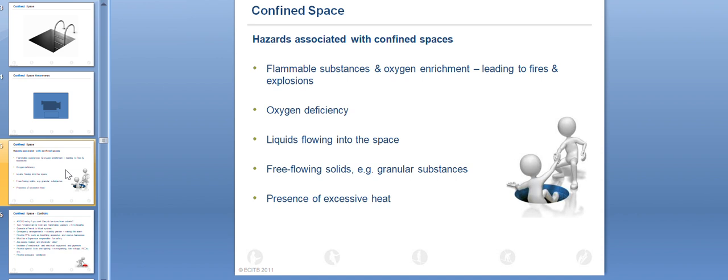And then, who is issuing the permit? Your safety officer. They must check the gas test. They have to check the oxygen level, hydrogen sulfide, carbon dioxide, and all other combustible gases. A proper test must be taken, and they have to write it on the work permit. Oxygen should be between 19.5 and 22.9, hydrogen sulfide 10 or less, carbon dioxide 0, and other gases should be 0. Then you can go for the confined space work.